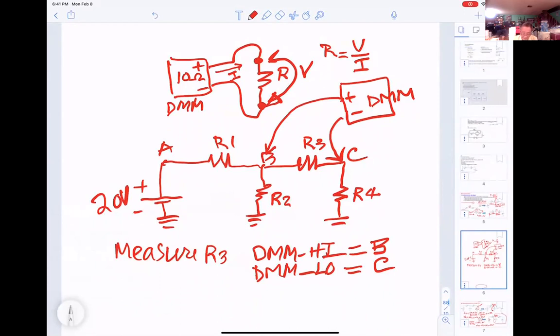When it measures resistance, it sends the current out, right? You see that? Right. So when the current goes out here, if you don't remove that source, the meter also gets this current here. See? So that's messing up, and you cannot measure.